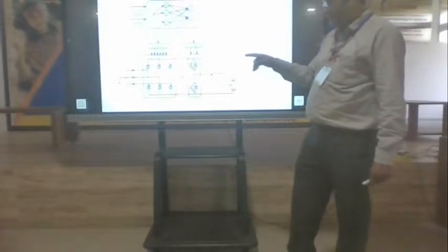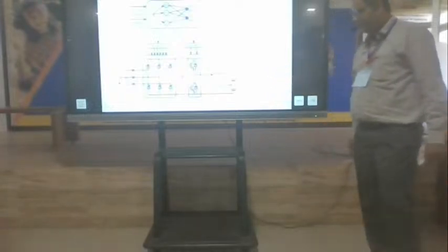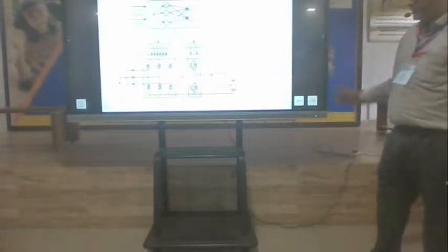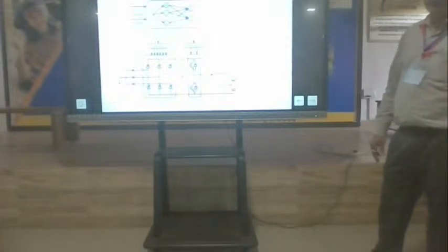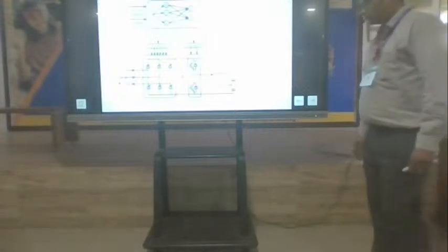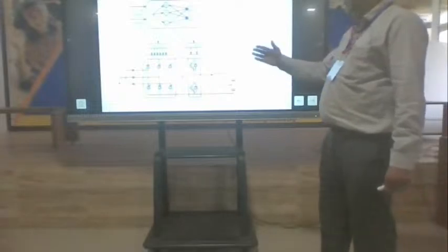It will have an AC supply, which is converted to DC by rectification, and then we have a capacitor DC link, and then it is converted to the proper voltage. Normally for the batteries in electrical vehicles, you will have a battery bus of 200 volts. Then it is given to the batteries. Similarly, in the reverse direction, if you are giving a supply to the motor, the current will flow in the reverse direction.